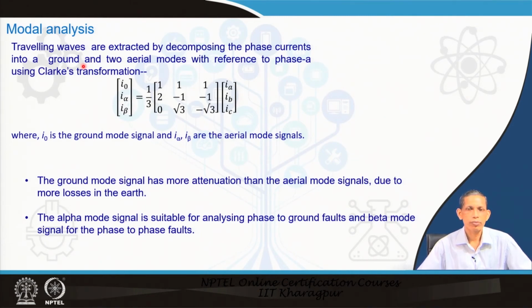Here the signal also contains the 50 hertz component, which is large. Upon that there is superimposed some high frequency component signal. This high frequency signal has to be extracted, which represents the travelling wave. Therefore, it requires other techniques. We will try to figure that out.